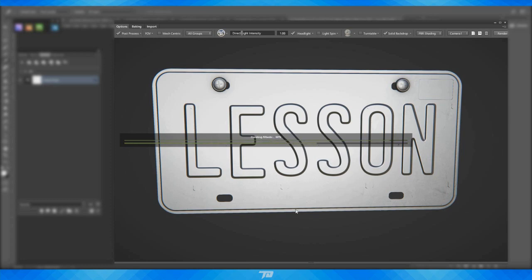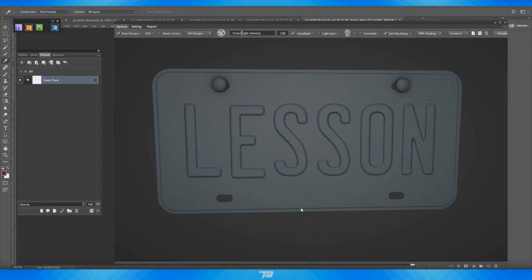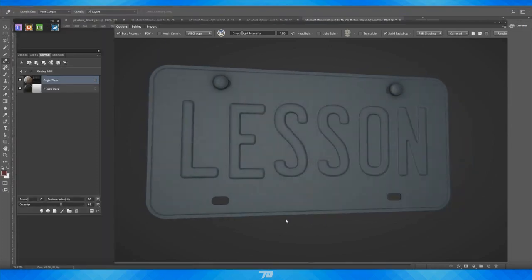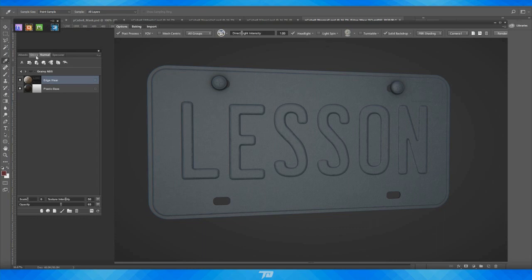And it's taken a while, so we're just going to let that do its thing. But essentially it's going to change the entire texture. We're not going to even recognize that we had that on previously. So it's a completely different look, so we are going to have to change a couple things. We want the normal information to stay the same, but for the gloss tab, we're just going to click on that here. And we are going to turn the texture intensity down to about 0, because we don't want any of the information to sort of shine through.